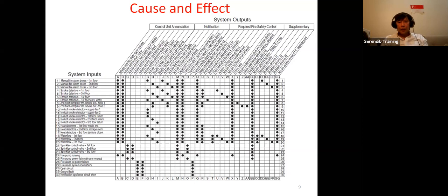As far as NFPA 72, duct detector is NFPA 92. Okay, so if we go along with NFPA, detectors need to be supervised, whether it's going to be called trouble or is going to alarm. But if the detector is somehow not configured to be monitored for its performance, supervisory and trouble, then it's not compliant. So try to make that detector compliant first.